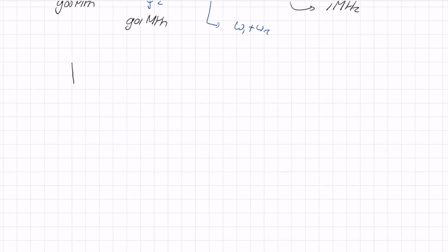If I have the antenna signal, first we amplify the signal a bit so it can enter the circuits that come after it, and so that those circuits don't add too much noise. And then normally the first circuit we meet is a mixer, where we mix with a local oscillator signal. That's just a very stable, clean sine wave.